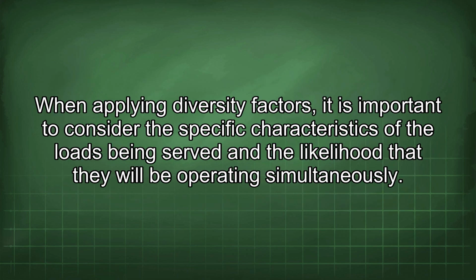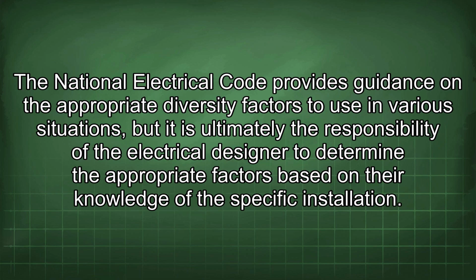When applying diversity factors, it is important to consider the specific characteristics of the loads being served and the likelihood that they will be operating simultaneously. The National Electrical Code provides guidance on the appropriate diversity factors to use in various situations, but it is ultimately the responsibility of the electrical designer to determine the appropriate factors based on their knowledge of the specific installation.